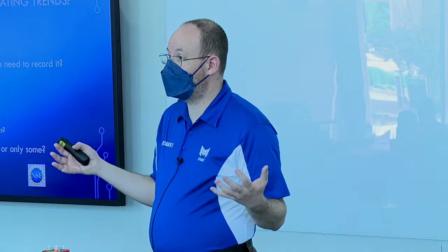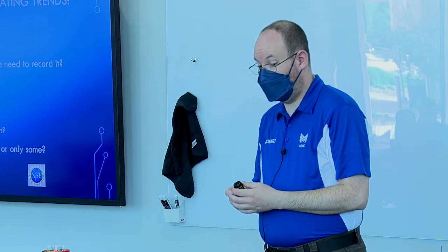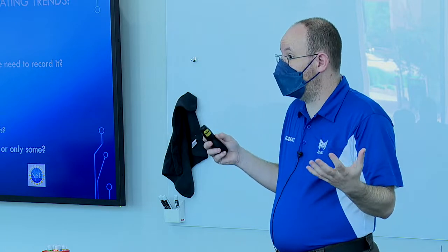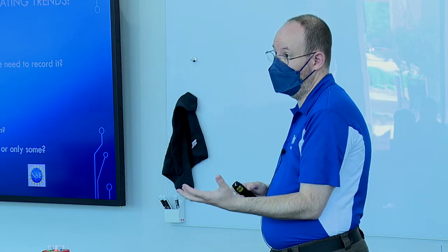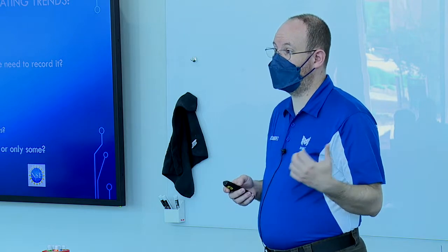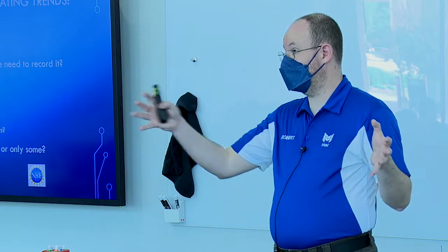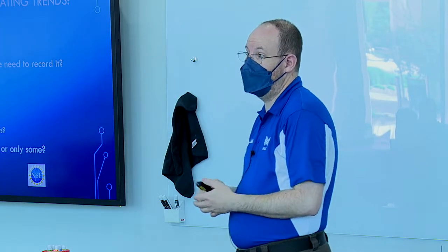If that's what they're communicating, you can't necessarily pull that data originally, and you're going to rely on the data that's being pulled from the system, which, to your point, if the system's in a questionable state, how can you rely on that recorded data? So you're correct in that in some systems, more modern systems, the last 15 years or so, it's pretty easy. It's definitely doable. If you get older than that, or systems that were originally installed before that, and then even expanded even into the last few years, they may still be running that proprietary communication bus.